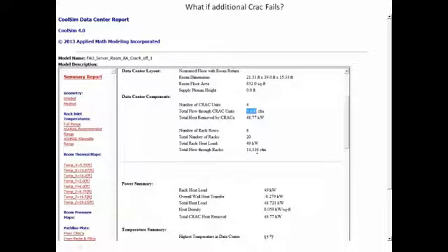So knowing the total cooling capacity isn't sufficient to be able to understand whether or not you've got a solid design. You have to also look at airflows, particularly in the case of containment, because unlike a natural convection room where racks can recirculate on themselves and at least be able to put some air across the electronic device, what happens here is if it's fully contained, you can't do that. The air won't come back around because it's blocked by the containment itself, and it'll starve. In this case, these would starve.